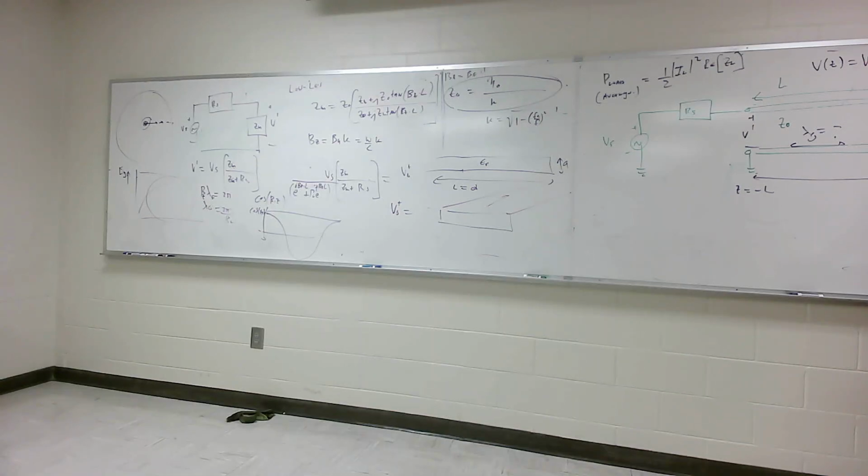The velocity that they propagate is different. Some of the power is moving at a certain velocity, the other power in the other mode is moving at another. So when you try to reconstruct that at the end, it's going to be garbled. It'll be something like aliasing. Y'all with me? No coherent processing. You only want one mode, which means you got to be below what's called the lowest cutoff frequency. That's the 1-0 mode. I'll spend time on that, but there is no lower cutoff.